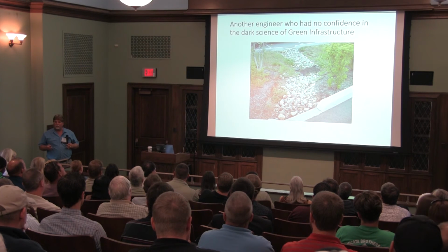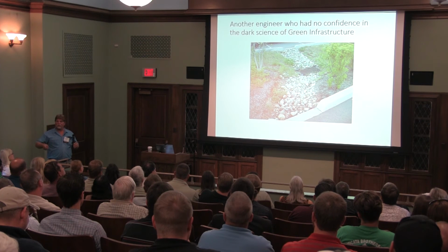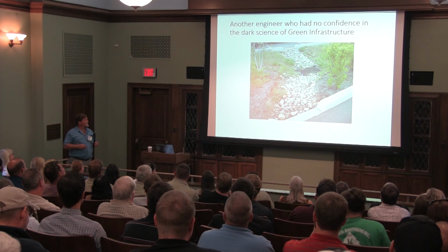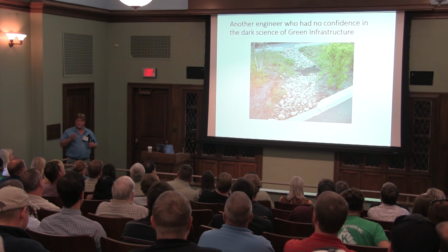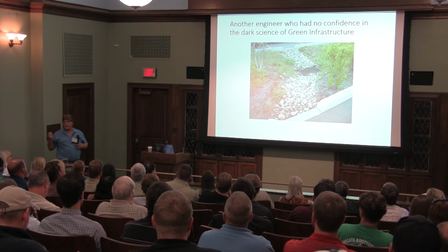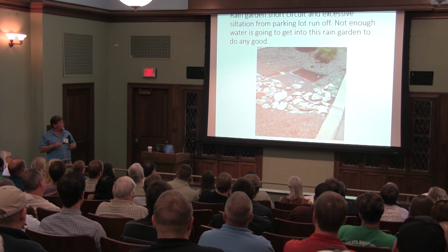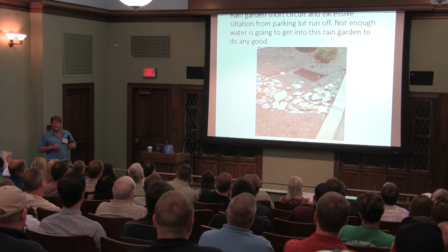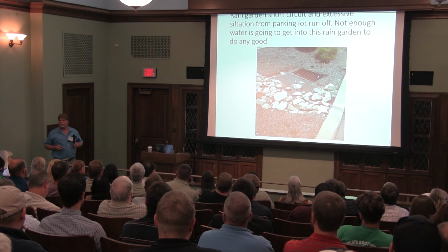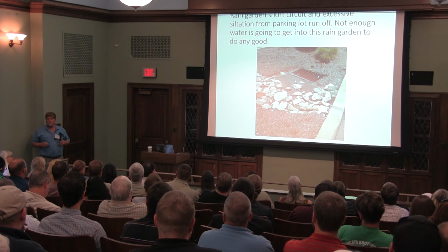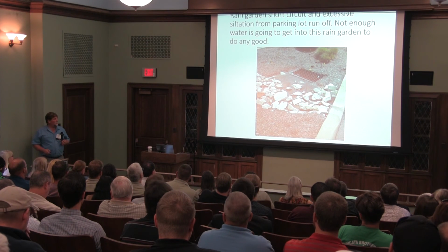It's defeating the whole point of having a rain garden. That opening needs to be upstream from that inlet, letting the water go into the soil. I cannot believe that this thing actually got passed through Conservation District, quite frankly. It's a short circuit. That's the same thing, different product. That's a short circuit. That's the opening right there. They short-circuited the rain garden because the engineer didn't want to be hassled with it, didn't want to have it not work. You build a rain garden, not getting any water into it. Okay? Both these instances.